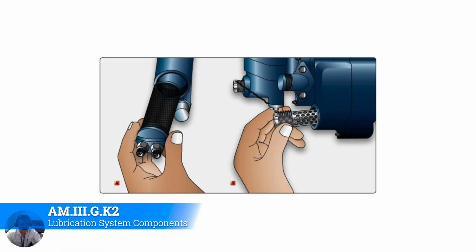Okay, so a couple other components in and around the engine oil tank. One here is going to be the scupper or scavenge oil screens. You'll end up doing these a lot whenever you do annuals, oil changes and stuff. You're going to pull the oil screen out, and that basically screens out a lot of large particles in the bottom of the engine oil case. Usually, if you find metal that's really big, this is where you're going to find it. Small ones you'll end up finding in the oil filter, and we'll get to that when we do oil changes.